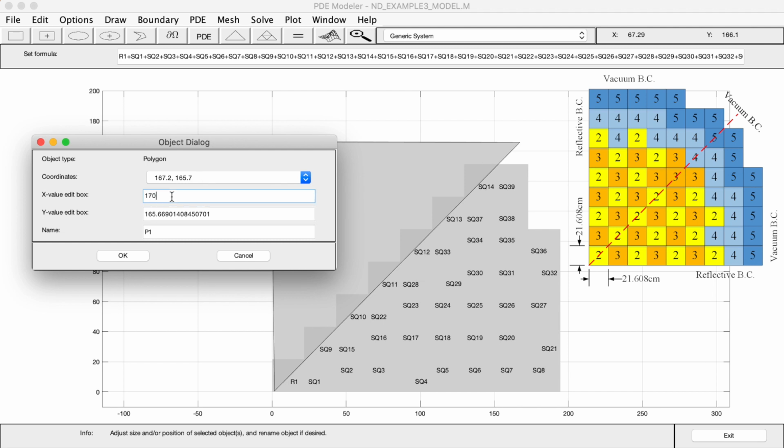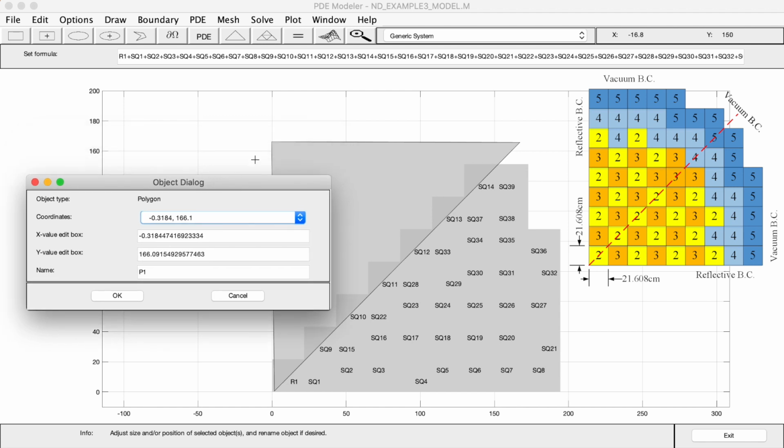If you do not press tab, and you use your mouse to change it here, this one is not changed, meaning its value is not saved. So 170 and 170. Make sure that this coordinate is changed to what you want. Then go to the next one. Here will be this point. So apparently it is 0, and y is 170.